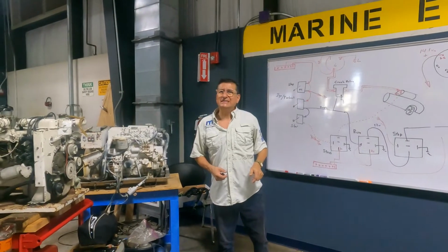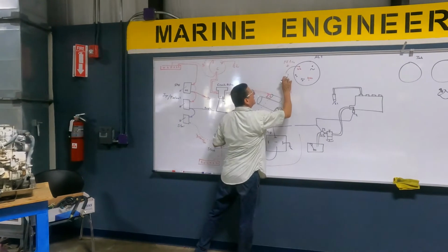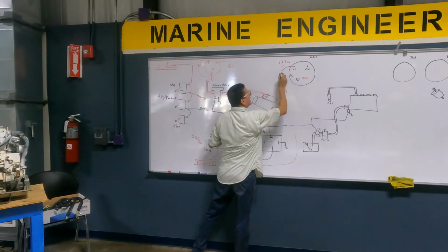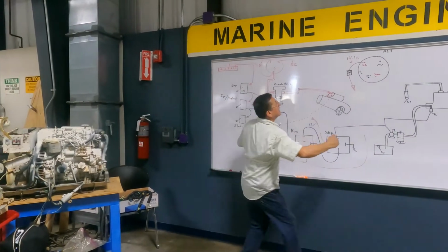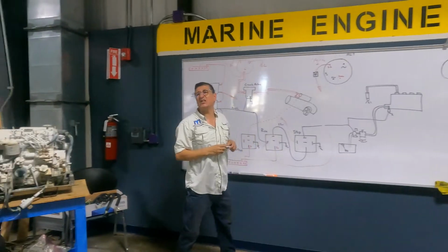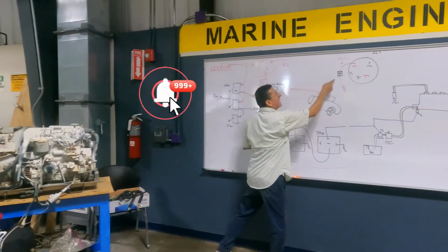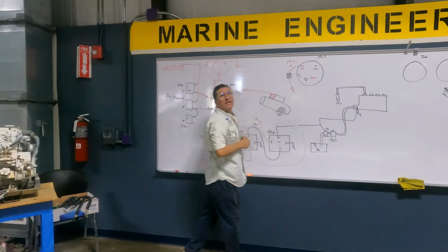No, you need a reverse diode. For that reason, you need to protect here with a diode. All the harnesses have a diode there to avoid current entering the stator and damaging the alternator. That diode allows current coming out, but not current coming in.